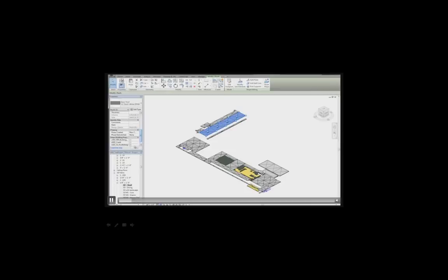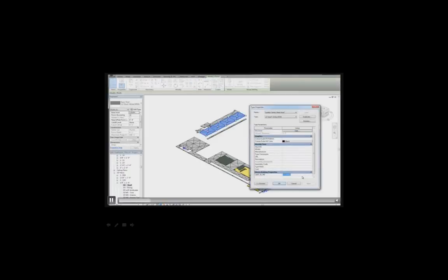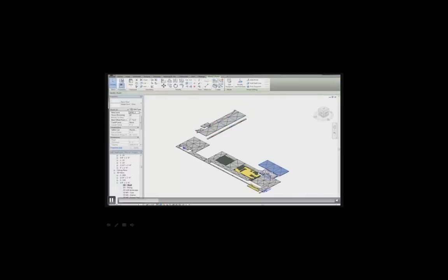So again, it's picking whether or not the roof is steep based off of that shared parameter. Just a yes or no, and you'll do that for all the roofs. Because they're instance-based, you have to select each roof and do it for that. You go to the type properties and then type in the SRI value, which is another shared parameter that you'll create, but that'll be type-based.